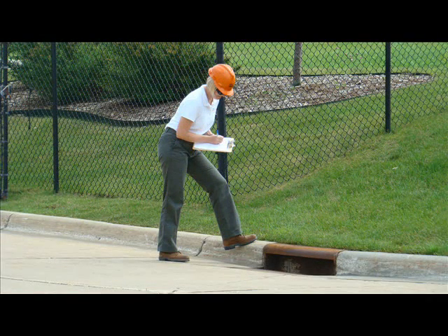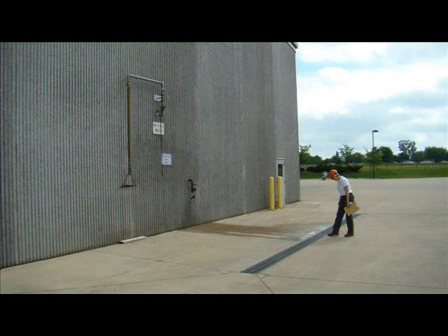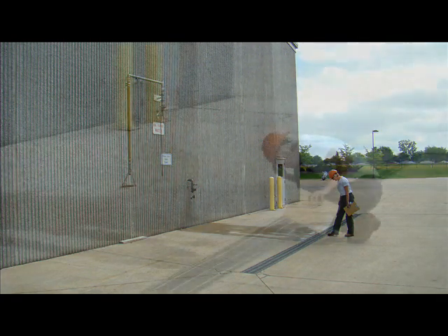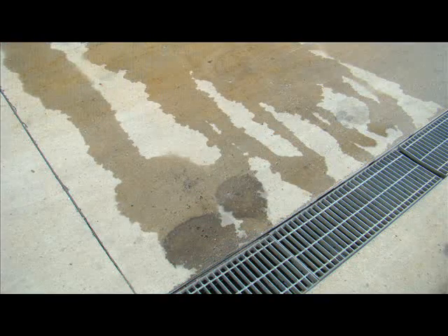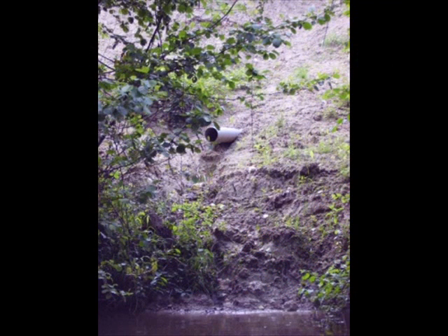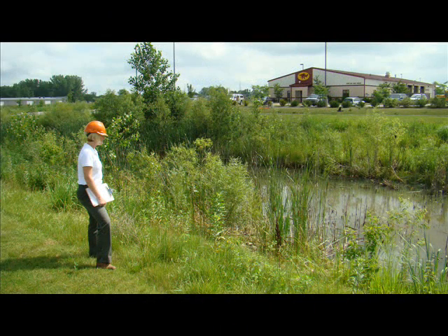Conducting the inspection. Signs of pollution. When doing visual inspections, you are looking for signs of stormwater contamination. During dry periods, look for any presence of stains, odors, residue, and other evidence of pollution. Inspections should also be made at all stormwater outlets during the first hour of a storm event to look for the presence of floating and suspended materials such as oil and grease, turbidity, discoloration, foam, and odor.